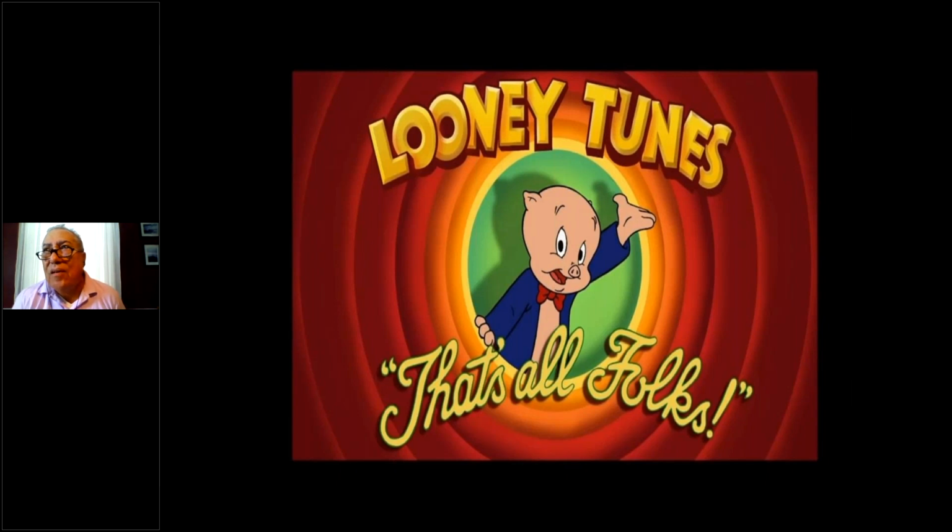But keep one thing in mind though. Steam boilers aren't particularly efficient compared to water boilers, for several reasons. It's different technology, so they're not greatly efficient, but they're okay by today's standards. I have a steam boiler in my house. It's 2 years old. I get 82%. I can live with that. If I take the same boiler and make it a water boiler, I could probably get it up to 85 or 86%.